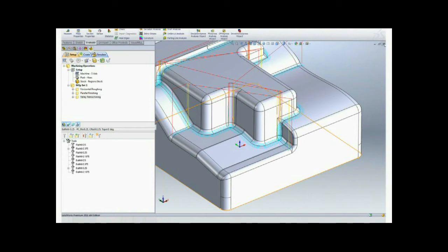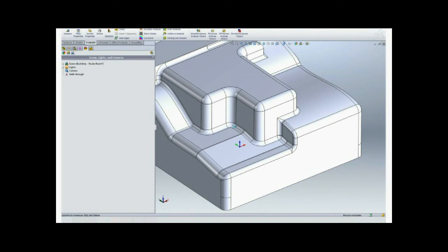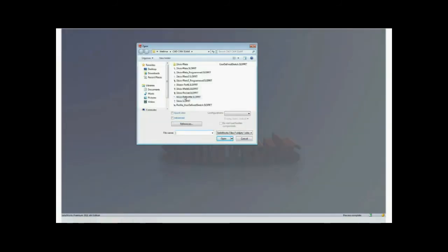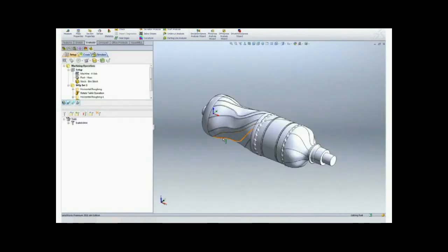We will now explore 4-axis machining methods. VisualMILL offers both indexed and continuous 4-axis milling. The indexed operations are performed using a table rotate operation, and you can apply a combination of both indexed and continuous 4-axis operations to program a part in VisualMILL. The part being loaded has features that need to be programmed from multiple orientations.